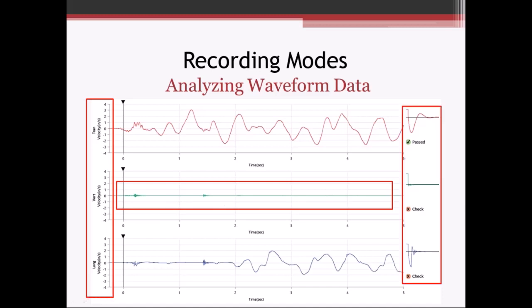And then over here, looking at our geophone test after the event was recorded, we've got something goofed up with our geophone here. Our vertical plane is all messed up, and our longitudinal plane really doesn't look all that good either. Transverse plane looks okay.